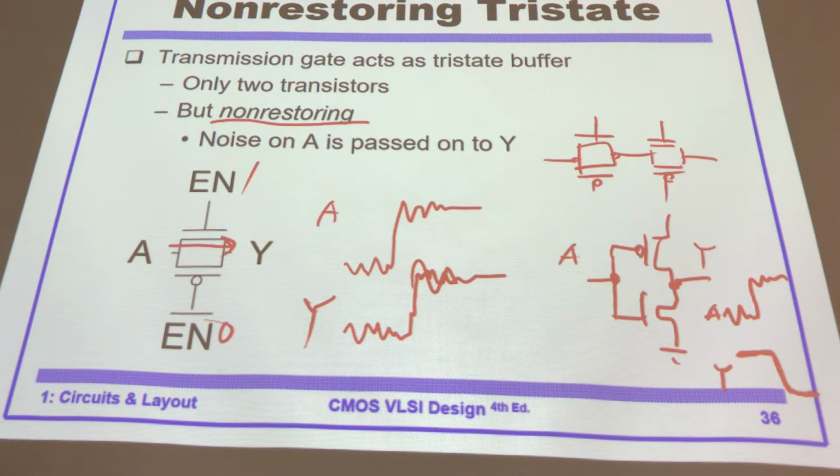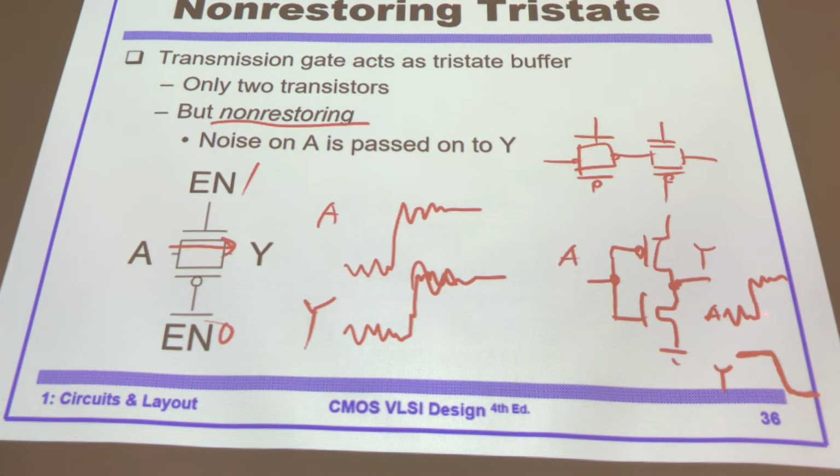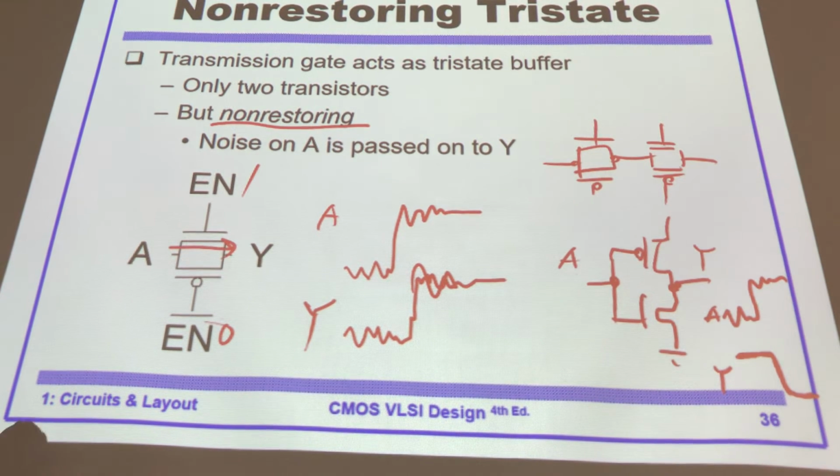We can still recognize you are still 0, you are still 1. We know that the gate can recognize that. And when it recognizes either 0 or 1, either the PMOS transistor is on and the NMOS is off, or the other way around. You are getting a good signal for 0 and 1. That's clean, 0 and 1.